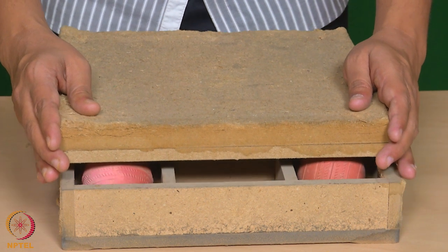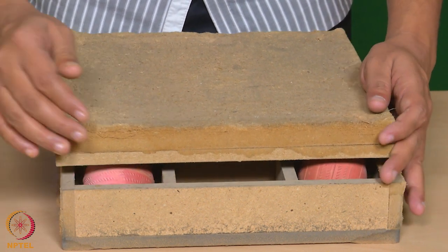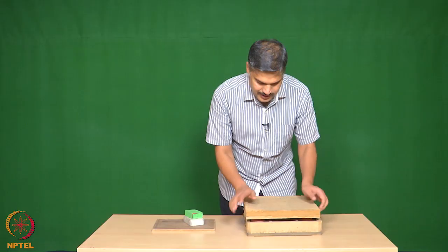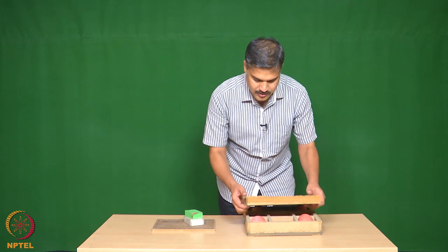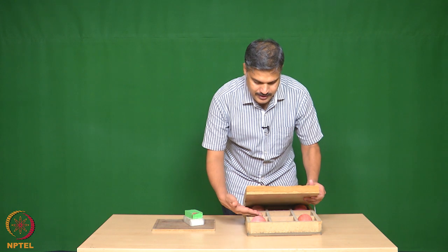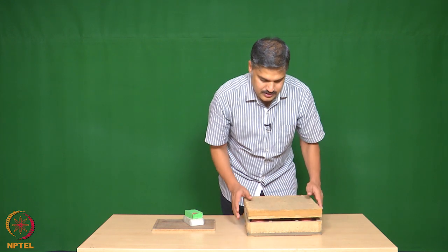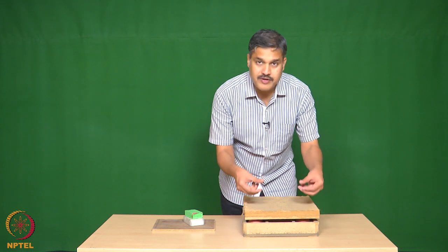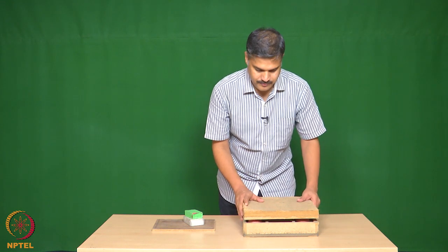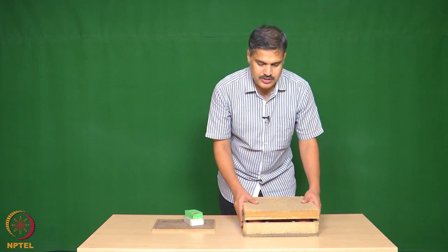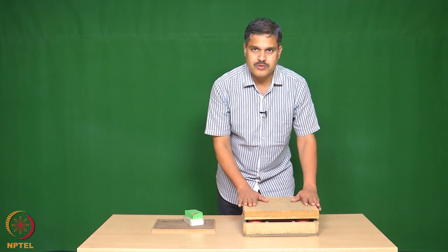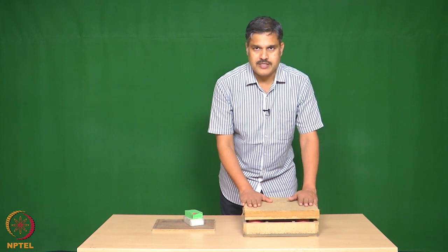If you look at this closely, it depends on how many bearings there are. Here in this case we have a full platform resting on these rubber bearings, but in some special cases these rubber bearings can be designed for individual columns. This base isolation is slowly becoming popular, and it is used for short period buildings.